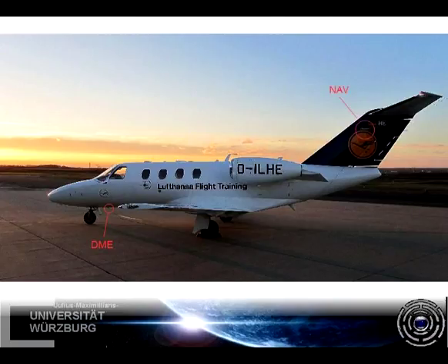The nav receivers that are used for VOR and ILS reception are located just below the horizontal stabilizer of the tail. The ADF sense and loop antennas are on top of the fuselage, just behind the cockpit. Furthermore, you can see the location of the VHF COM antennas on the upper and lower side of the fuselage that are used for voice communication, the emergency locator transmitter, GPS and other vital systems that require a radio transmitting and/or receiving capability.